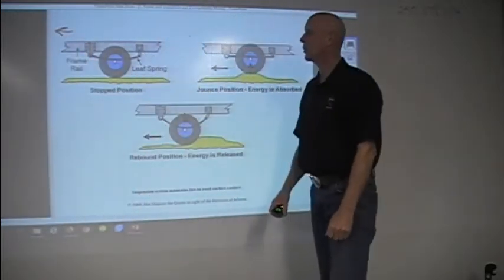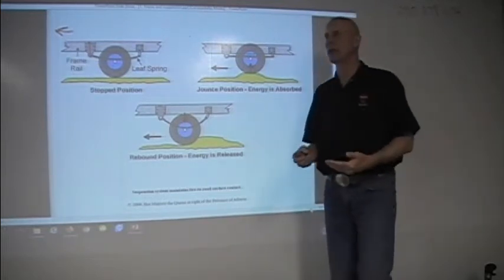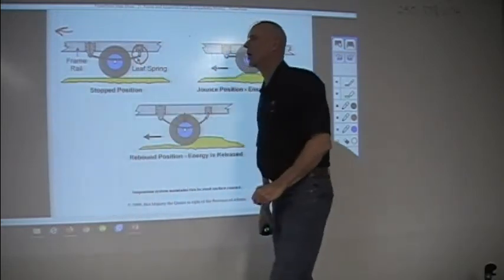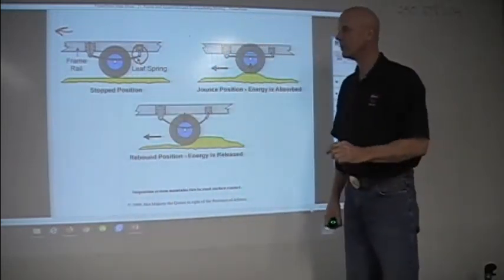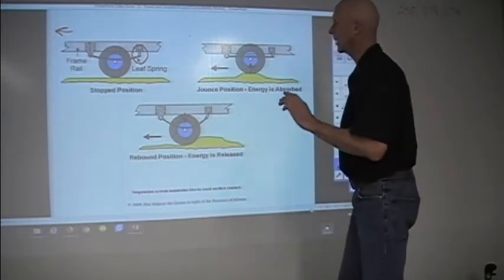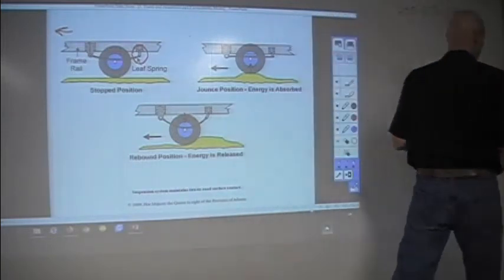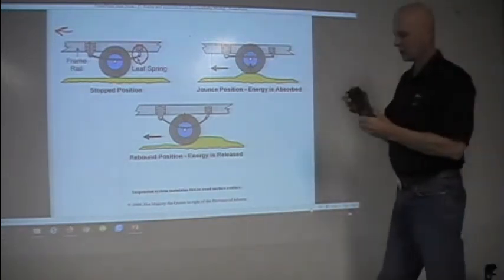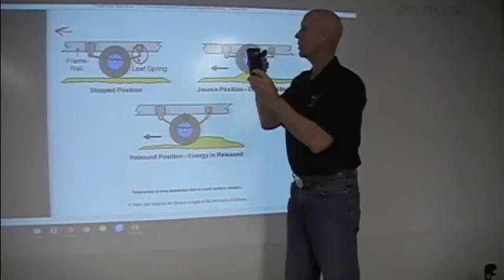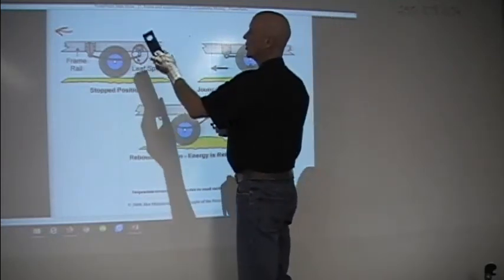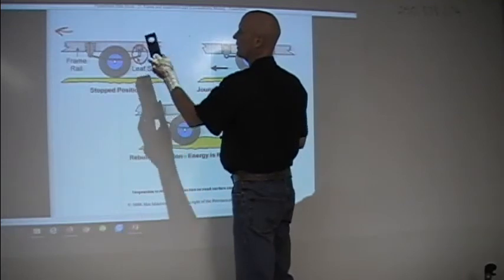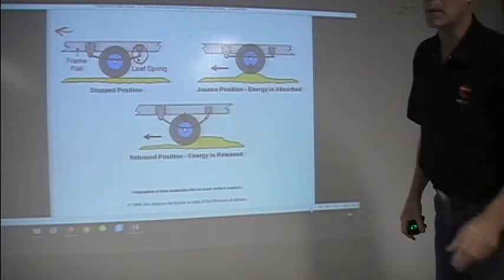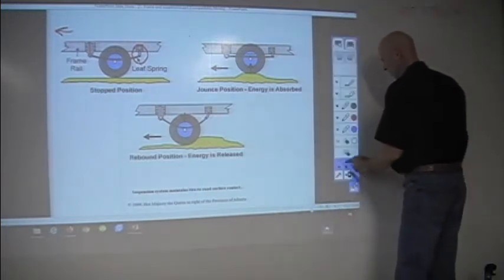Now our spring has to be able to change length as it moves up and down. So on the back of the spring we're going to have 2 spring pins and a link. That link joins those 2 together. Usually we have something that looks like this, where our upper and lower spring pins go in, and it allows it to pivot and move back and forth. That accounts for the change in the spring.